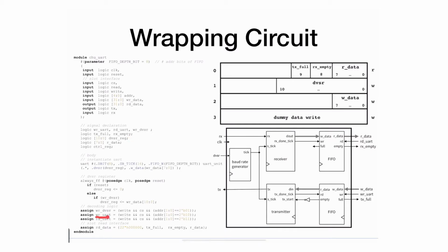The next one is actually a write to the UART, which is actually the ones in here. What does it do? It tests, is my offset number 2, which is actually this one here. If the offset is 2, I'll just basically write whatever the processor wants to write into it. So basically, I'm connecting that write to that processor, and that's it. There's nothing else to it, and this is actually connected somewhere in here. It's called WR UART, and that's it. And read UART in here is also the same. So what the read UART in here is actually related to the signal.